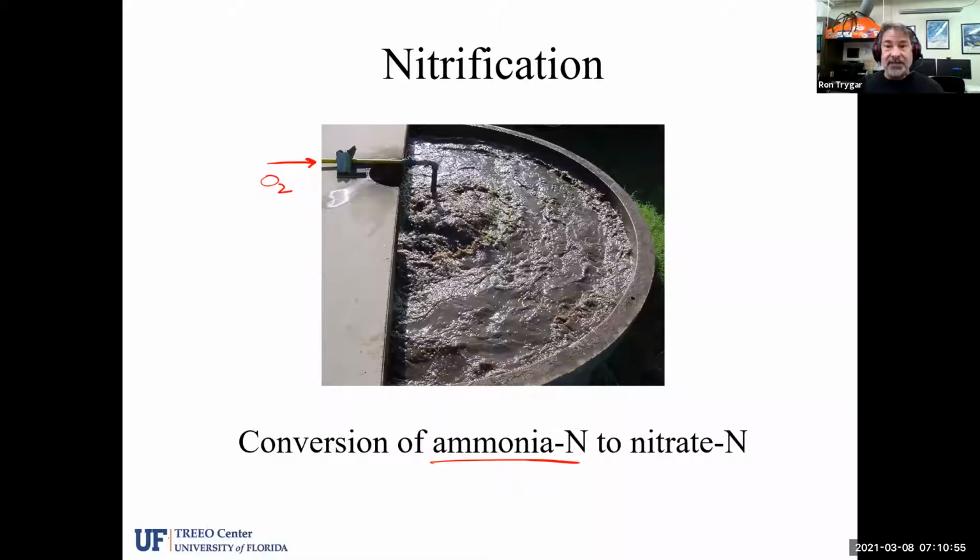In fact, if you wanted to know how much ammonia was present and how much ammonium was present, we would have to run an ammonia test. But at the time of collecting the sample, we would also have to collect the temperature of the liquid at the time of sampling, and the pH at the time of sampling is important. You could measure dissolved oxygen as well, which is also measured in the field as a field parameter.